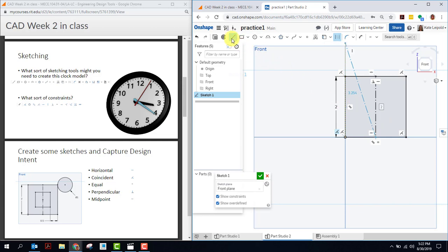Okay. Click on the line tool to disable it and turn on the center point rectangle. And we can again take advantage of that midpoint option to put the center point rectangle at the center of the construction line. While I'm placing this, I notice it's construction geometry, but pressing Q while I'm placing it toggles off the construction tool.